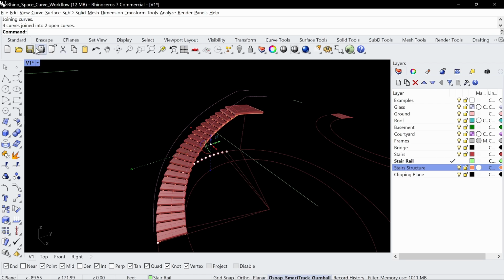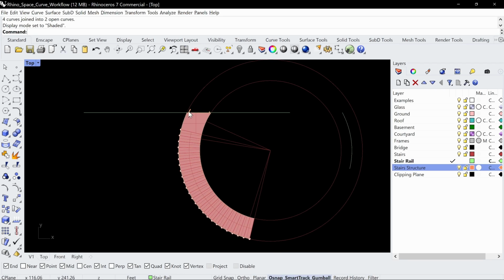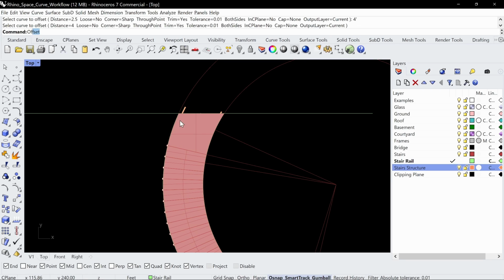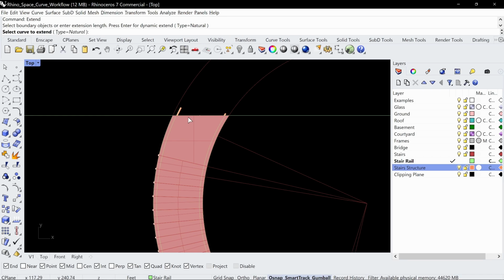So if I go to plan view, let's go to shaded. So we have this piece here. So I want to offset. Let's offset in like 4 inches. So we'll take this here, offset 4 inches like that. And then offset 4 inches like this. And again, don't forget, this line is where that floor slab is. Once I hide everything, you'll see. Or unhide it and show everything.